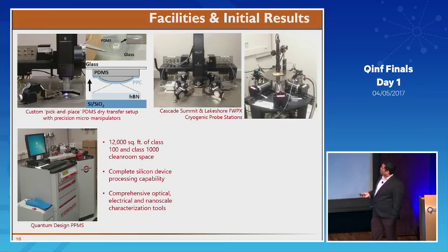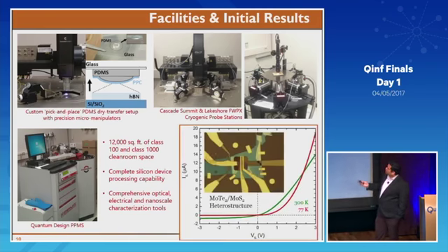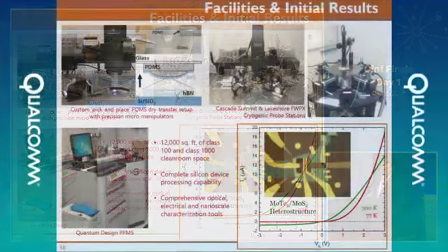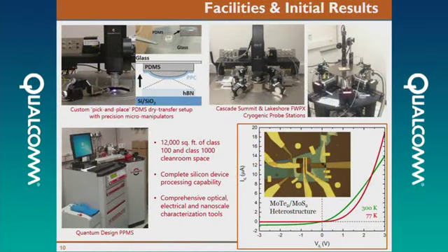So these are the initial results we want to show here. We have already started working on these heterostructures made of MoTe2 and MoS2. We have demonstrated the PN junction diode using those heterostructures, and these results were recently presented at the APS March meeting, and we want to go to the next step of the Esaki tunnel diode and towards the BiSFET.